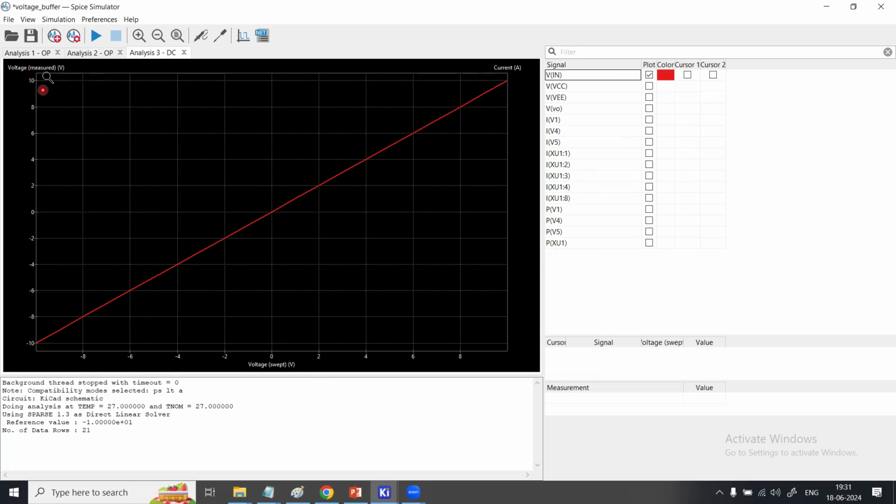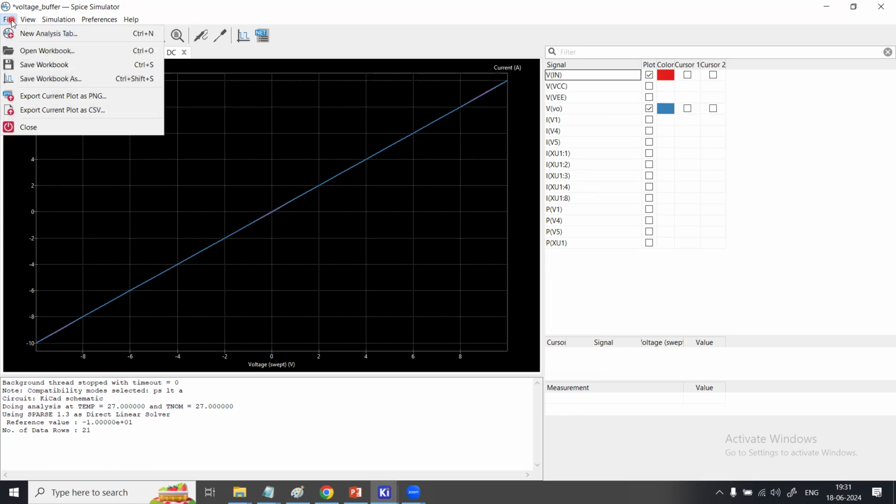That's the voltage. Now I am interested in the output voltage here. Oh, great. Look. So faithfully the output is following the input. So it's a voltage follower or buffer circuit. Okay, that's really good swing. So this is a real world design. Okay, we are not doing a generic op-amp simulation. You can really match with your specification, depends on that.